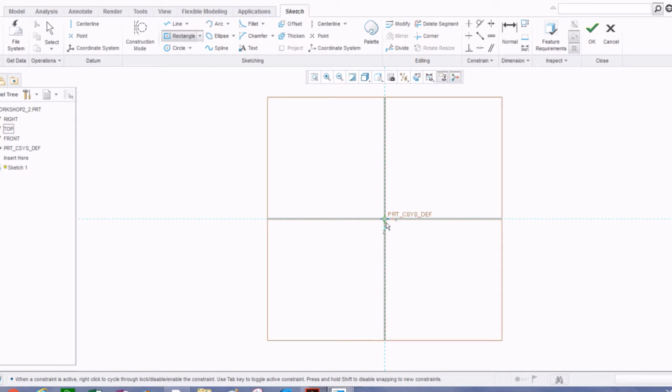And since the top profile is a circle, I won't have to dimension away from the axis. It'll automatically generate, which is really nice. Grab that relationship again. This time I'll show you how to put it in case you forgot. So if you have some kind of weird shape like this, you want to go right or left and center click. And you want those to be equal to each other.